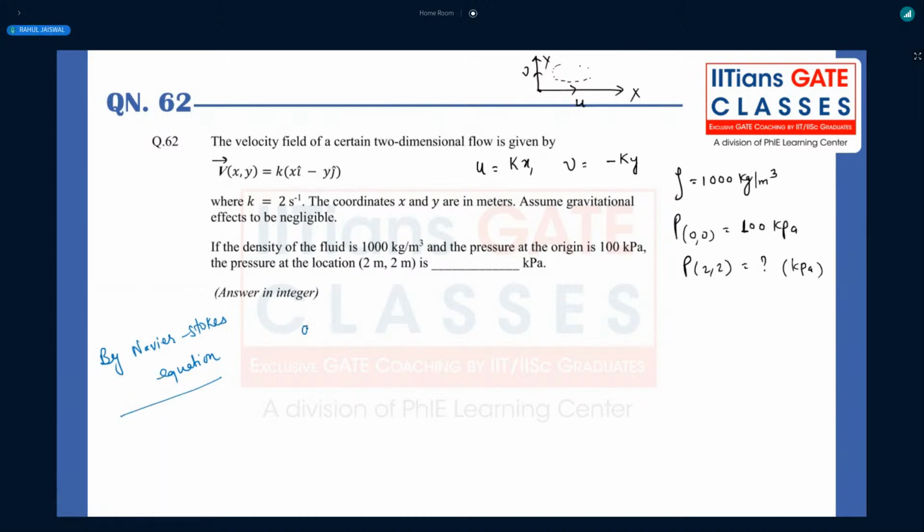now if you write the acceleration, see what the Navier-Stokes equation is. Net force is equal to mass into acceleration, right? That force will be pressure force, gravity force, and viscous force. So here we will write ax as minus 1 upon rho, dou p by dou x, right? That is what we are considering, only pressure forces. Viscous forces will not be coming in here.